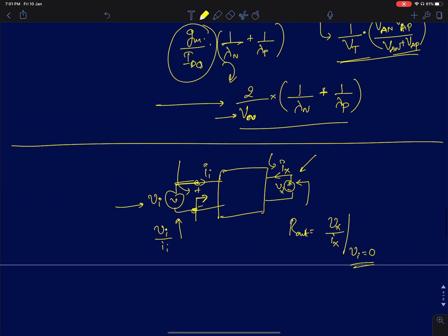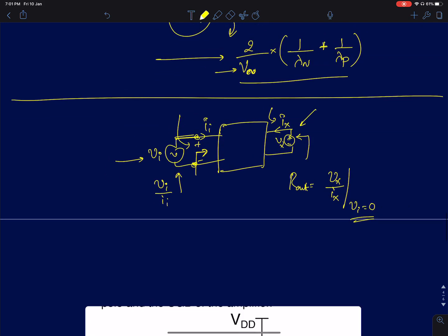And I haven't done it for these two circuits. For a common emitter configuration, essentially you're looking into the gate of a MOSFET, the input impedance is obviously infinity. Okay. And for a BJT, you're looking into the base terminal, and the voltage is applied across base emitter. So it will be simply r pi for a BJT. And for the output resistance for both the devices, you're going to short the gate and the base for a BJT, and you're going to look at the drain and collector. So that will be simply ro for both the devices.